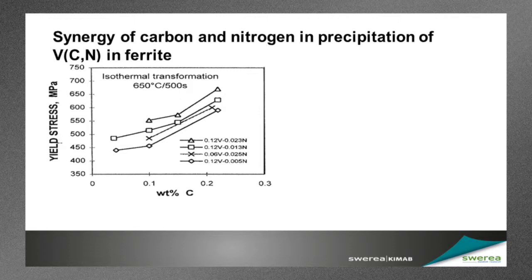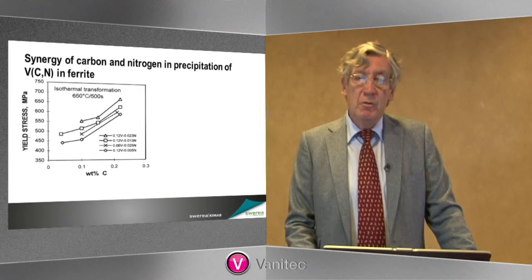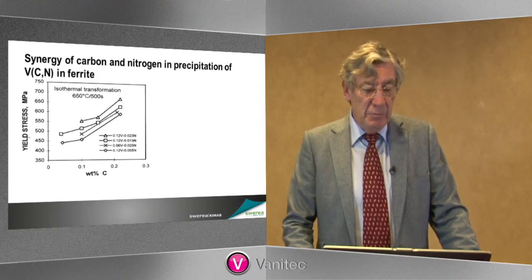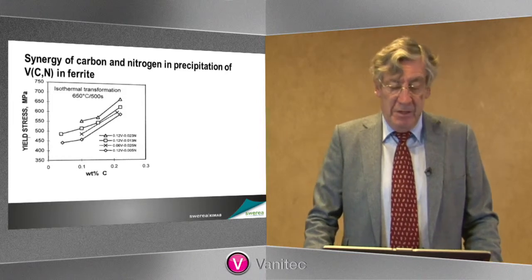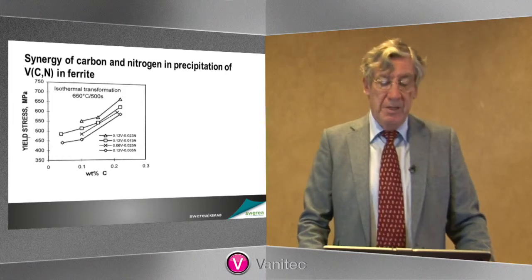That's old hat. But actually it isn't true when you come to look at the yield stress of low carbon steels. The conventional wisdom is actually that the carbon content has no effect beyond how it may affect the grain size. The excess carbon will be in the form of pearlite, and that may affect and increase the tensile strength of the steel, but not the yield stress. So we wouldn't, according to conventional thinking of HSLA steels, expect the effect of carbon to be at all pronounced here. But it obviously is. We're increasing by something like 150 megapascals as we increase from, say, 0.04% carbon to 0.24% carbon.